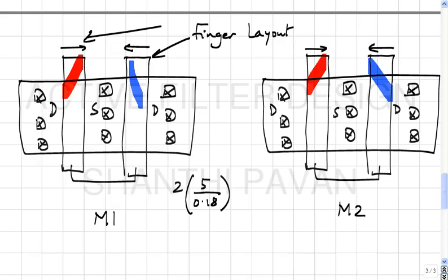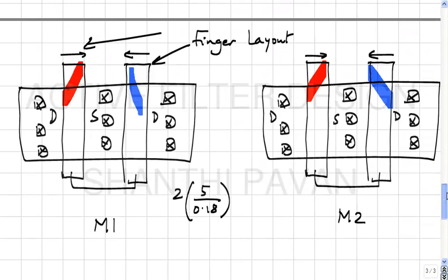Yeah, okay. So if you have 3 fingers, for example, you always have the odd man out where current is traveling in some direction. Now, if you copy and paste somewhere else, if you are not careful, you can always make a mistake, and the singleton in the pasted version could have current flowing in the opposite direction.